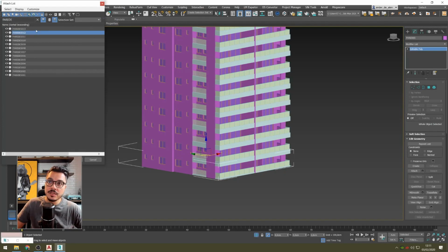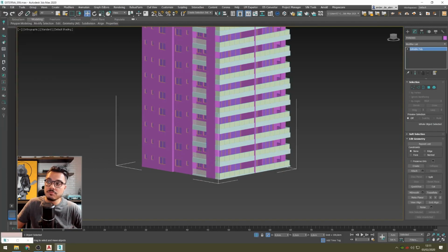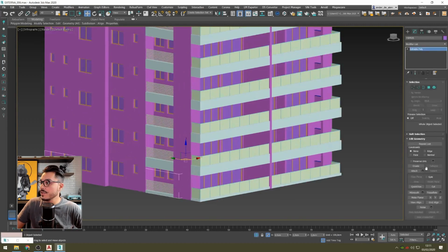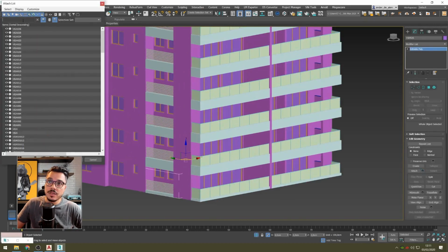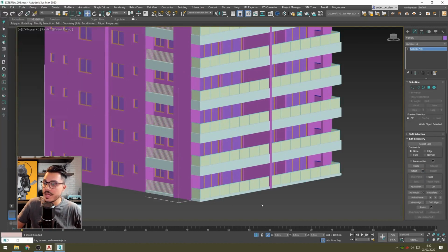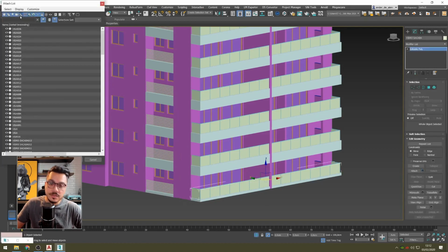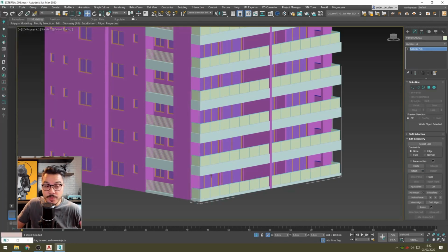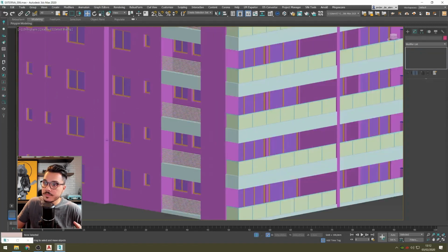easy. I will click here, walls. I will select all the walls. Done. Walls. All the glasses, click here, attach it, click here in search, glasses, then all the glasses in the tower, all the balcony glasses, attach, glass, not that one, it is this one, balcony glasses. See how important it is to rename everything.